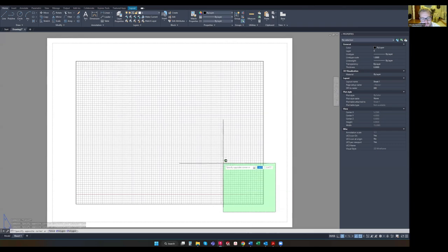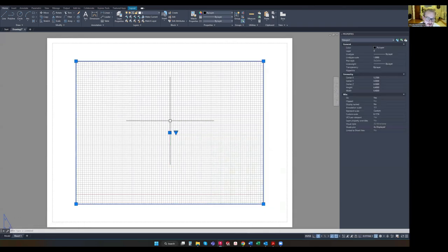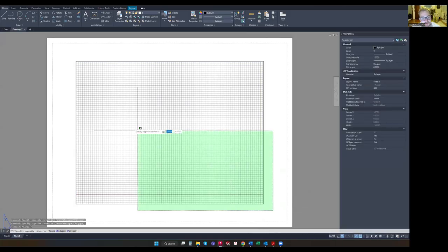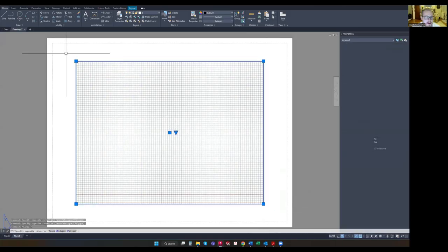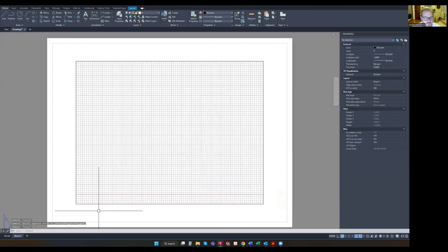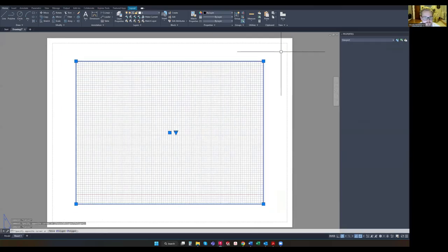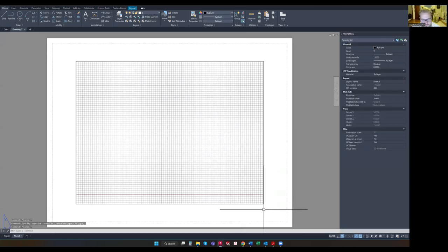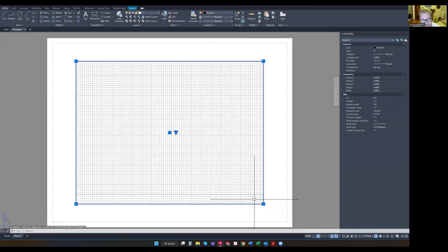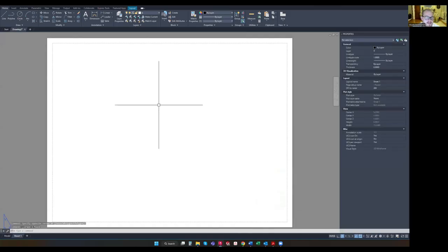Conversely, if we click and pull to the left, this green rectangle, you don't have to encompass the entire line or the entire box, like you do with the right drag. So remember, with a right drag, you have to do the whole thing to select it. I'm clicking escape to deselect, just so you know. To select this, usually I would just click it like this, do a left drag over the corner. It selects the entire box, and we're going to go ahead and delete that.